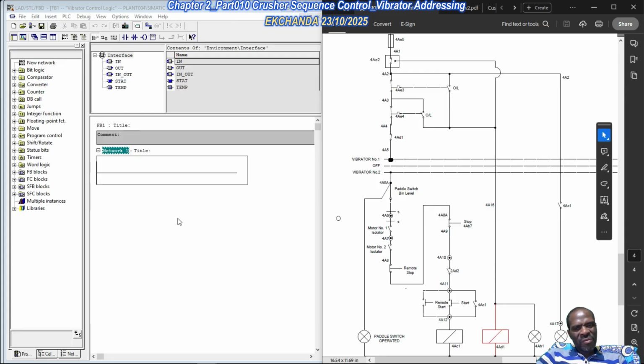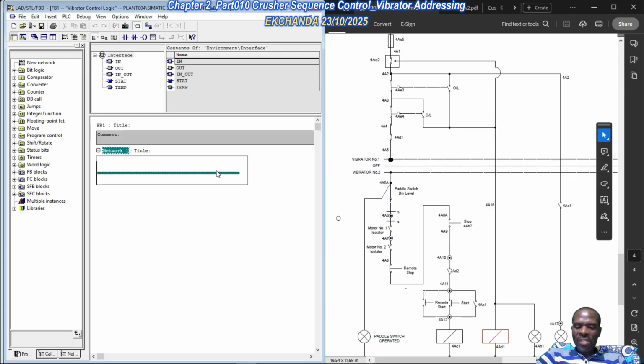Because of the way the protection inputs were being validated, we can modify this, and we won't even bother with latching these protection states. Why? Because when these signals were being passed to the PLC and the protection inputs were being validated, we needed to reset those inputs to normalize the system.